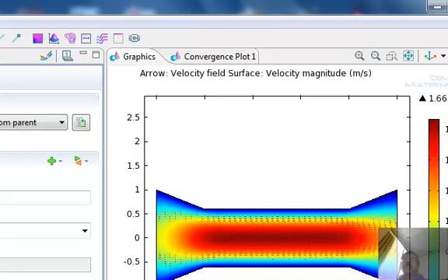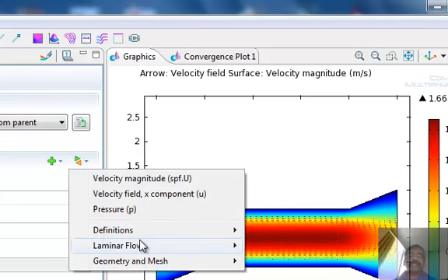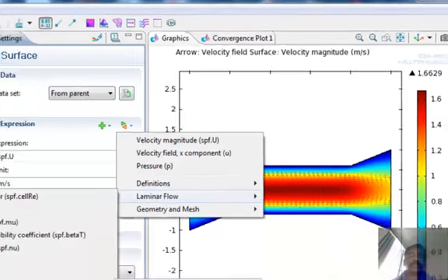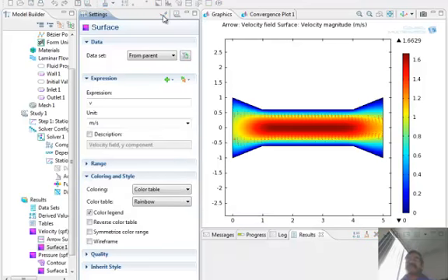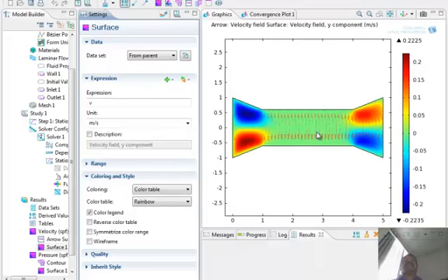The magnitude of the velocity is something like 1.6. Now I want to look at the magnitude of the Vy component. So I go in there and plot only the y component. You can see where the y component is large. Remember, green is 0. So in the middle of it, there is no y component velocity. And here it is negative, it's positive. There it's negative, it's positive. So you can get very quickly an overall picture of what the flow pattern is by selecting and plotting and trying to digest all the information.